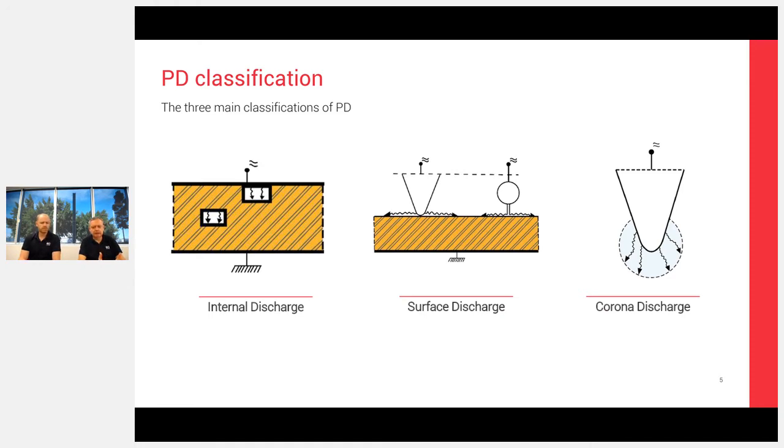So with the compound insulated cable box that had blown up on the previous slide, the first warning you would have had is that it disruptively fails. So no prior warning before we get that explosion occurring, and that's due to an internal type discharge. When something is happening across the surface of the insulation, so much like in that bus bar situation, you do get a potential chance with a visual examination of the bus bar to see it. But you also get some byproducts, nitrous oxides and ozones. The smell can permeate from the switchgear, and that can give you earlier warning.